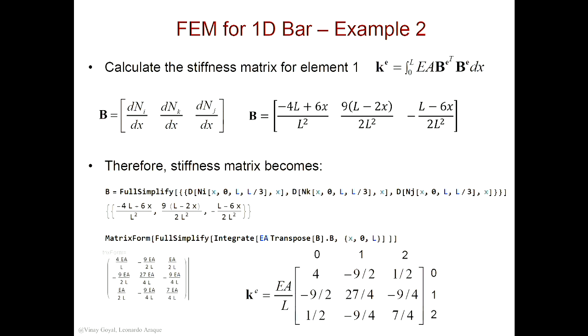Then I went in and calculated these derivatives. And that derivative gave me these numbers. I did that here. I took those derivatives here. So this is how you get a derivative in Mathematica. You put a D in front and then comma x. Since I have that expression for Ni already, it will give me that derivative automatically in this format. Okay? So I did it for each of the shape functions. All I did there was to calculate what you see above. Okay? Follow? Yeah. Very good.